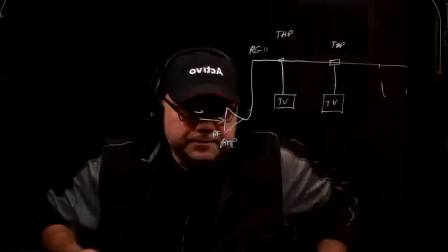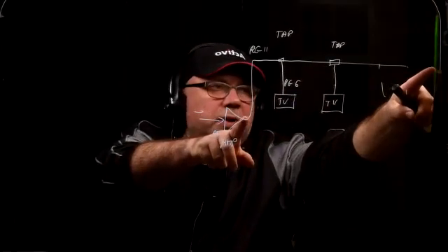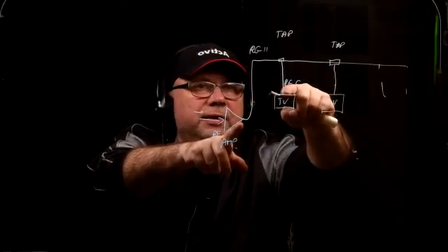Here's the thing: over here, by the way, this would be RG11 cable. This could be RG6 or RG59, because from here to here you might have 200 or 300 feet, and from here to here you might have just 40 feet. So that's fine.